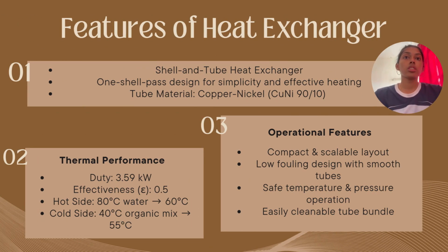For the features of the heat exchanger, the first is it's a shell and tube heat exchanger and it has a one shell pass design for simplicity and effective heating. The tube material that has been used is stainless steel 316L. And for the thermal performance aspect, the duty is 3.59 kilowatts.